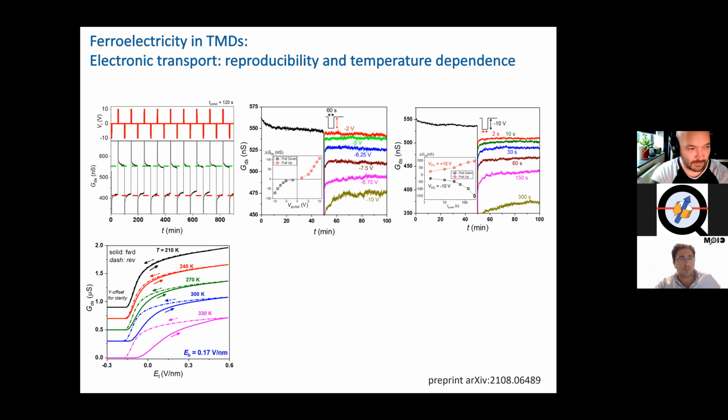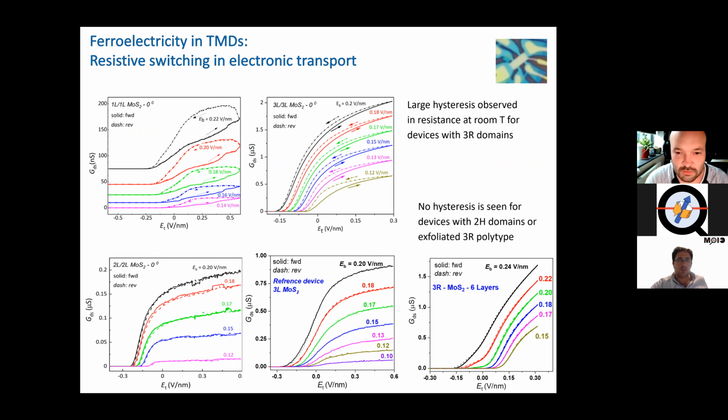That's a good question. And the easy way, so there are two components here. We're trying to build a model for this now. At the moment, it's a very basic understanding, trying to explain the experiment. So one way to look at it is the device is asymmetric. So you basically have this delta across the bilayer, which adds a little bit of electrons on one side. Now, if it's a top layer and you're gating from the top, that results in higher overall net concentration, which has higher conductivity. If it's the bottom layer and you're gating from the top, then the overall concentration is not as high, and hence that.